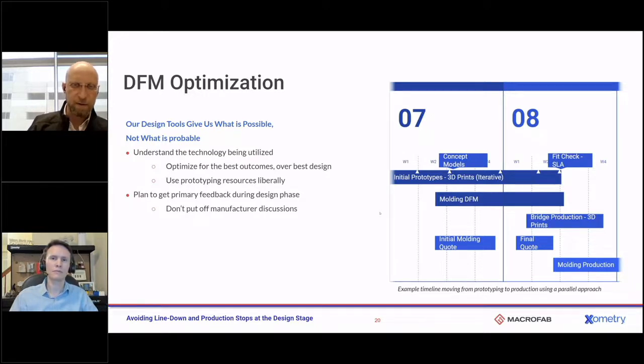One is, depending on the process and the overall complexity of the board, we can actually paste both footprints in some cases. But when that's going to be an issue, how we'll typically solve that in manufacturing is pretty straightforward. If everything allows us, we'll have both footprints cut out of the stencil, and we'll Kapton tape over the inner one we're not using. The outer one typically doesn't matter as much because there's nothing to interfere with there. But if there's going to be interference with a larger part by having put paste on those pads, or if we're concerned we're not going to be able to get good flux movement out of those lower pads because it's really tight, we can put Kapton tape or any other strategy over those actual holes in the stencil at stenciling time. And that's just a lot faster and cheaper as long as it's going to work.